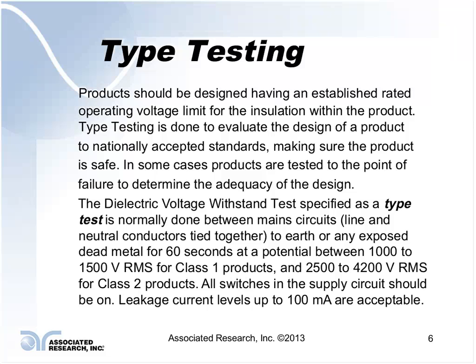The dielectric voltage withstand test, specified as the type test, is normally done between main circuits, which is line and neutral conductors typically tied together, and high voltage is connected to these circuits, and the return is connected to any exposed dead metal or to earth. So we're testing essentially the primary input of the product to any exposed dead metal.